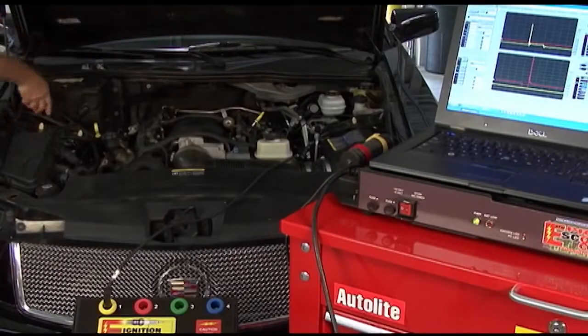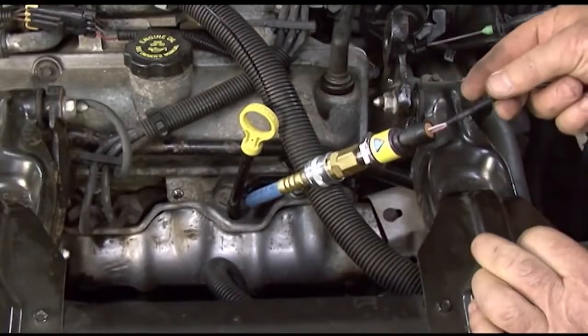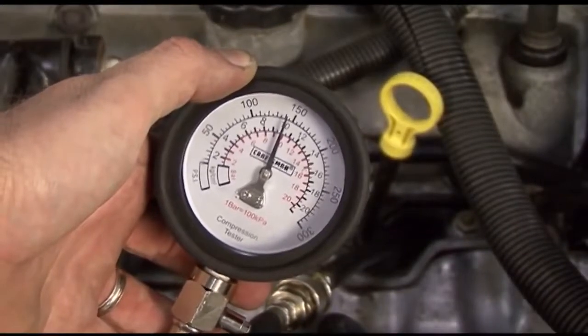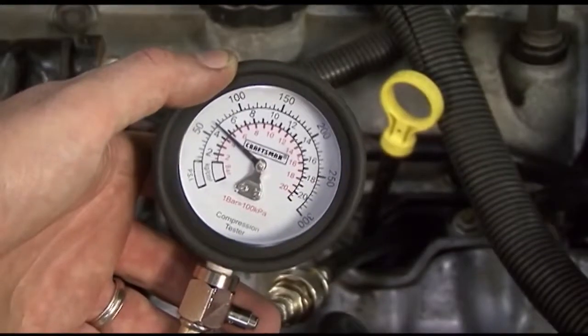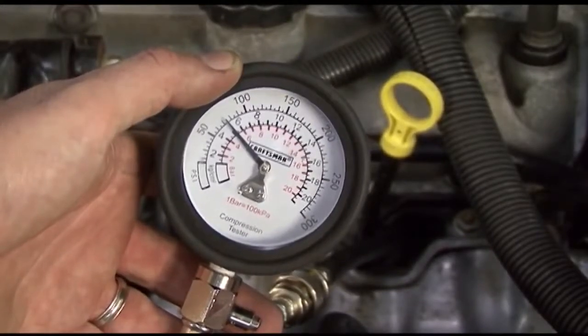There are many potential mechanical causes of misfires. Start by checking engine compression on the offending cylinder. This can be done with a big box analyzer or an oscilloscope and a high amp probe. If these diagnostic tools are not available, start your normal compression testing on just the cylinder that you detected the misfire on. Record the cranking compression reading. Then start the engine, bleed off the pressure in the gauge, and re-record the compression at idle.